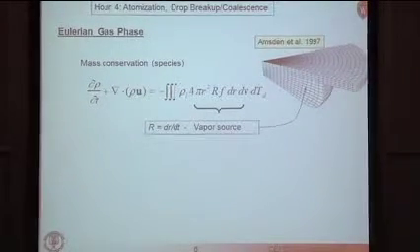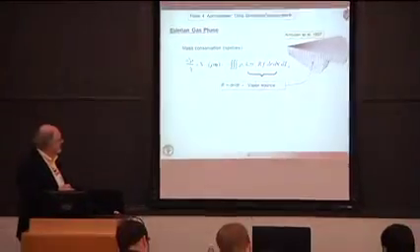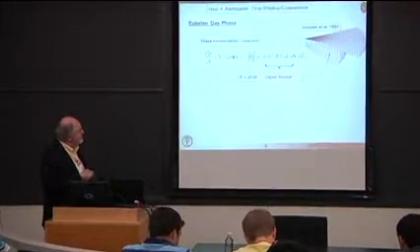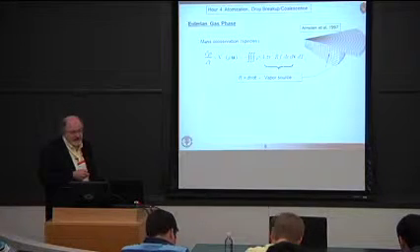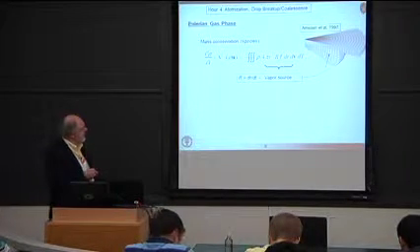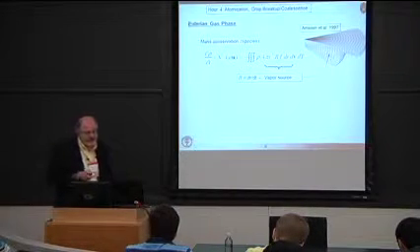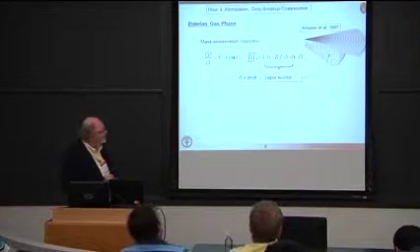So now we can take a look at what would be required to implement that spray model in a practical calculation, starting with the gas phase equations. Last time we spoke about mass conservation, and we had a source term on the right-hand side accounting for spray effects. As those droplets vaporize, they contribute vapor to the gas phase.